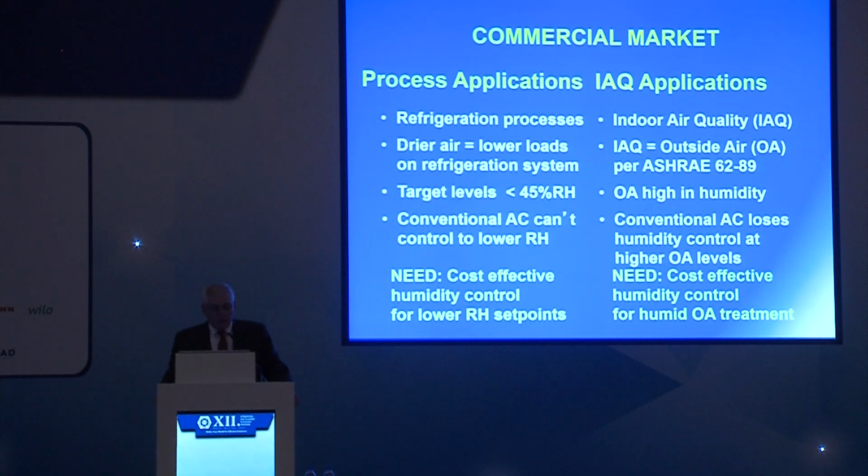So if we look at where desiccants have been in the commercial market, many times it's in refrigeration and process applications when we need very, very dry air, less than 45% relative humidity. Many times conventional air conditioning is either too expensive or can't make the very, very low dew points or frost points required. In some applications you actually need frost points below 0 degrees C, so desiccant rotors are very applicable to that.